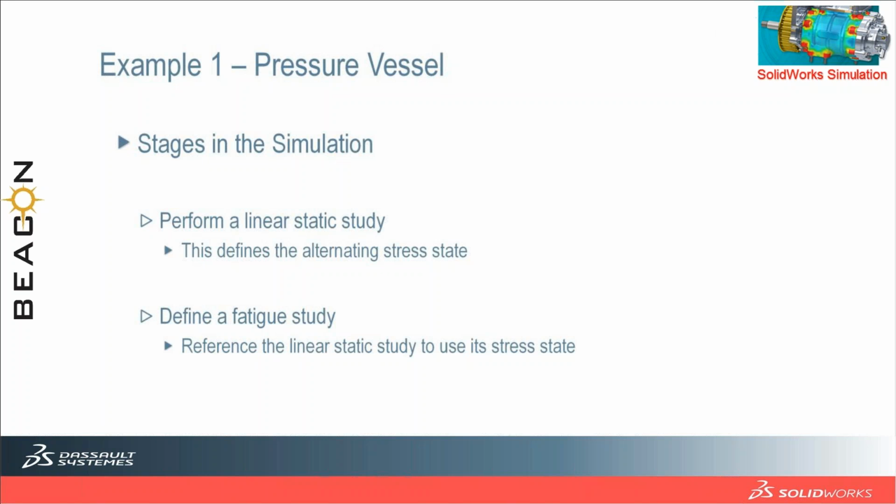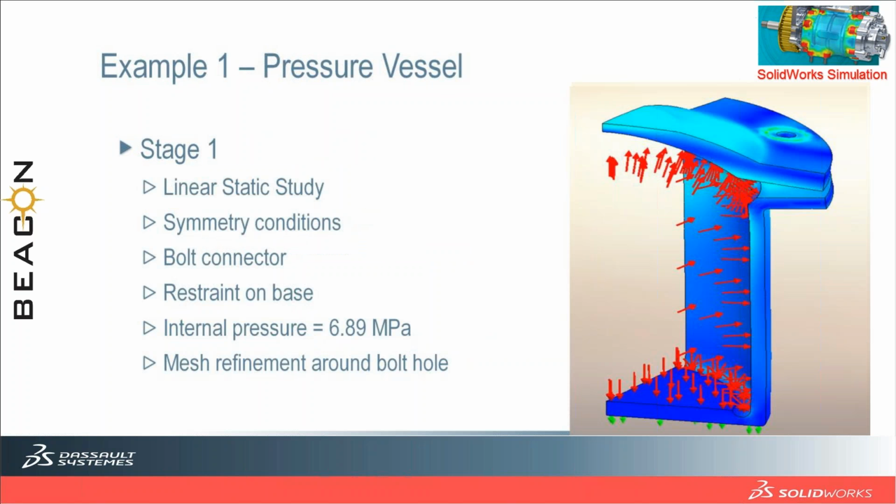As a customer, sometimes he will ask, what is the durability of your component? How much guarantee are you going to provide for this? As a manufacturer, I must be sure how much it's going to withstand without a failure. To get that value, we have to perform this fatigue analysis, and we have to define the number of cycles, and as I said, the SN curve is required here. So again, this is stage one, the linear static analysis.